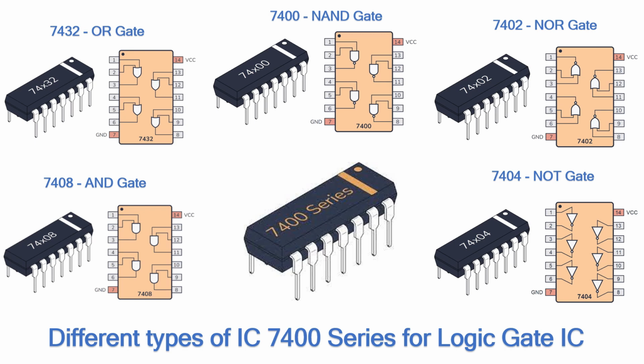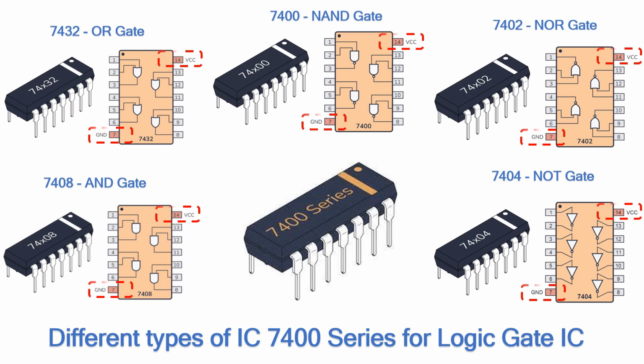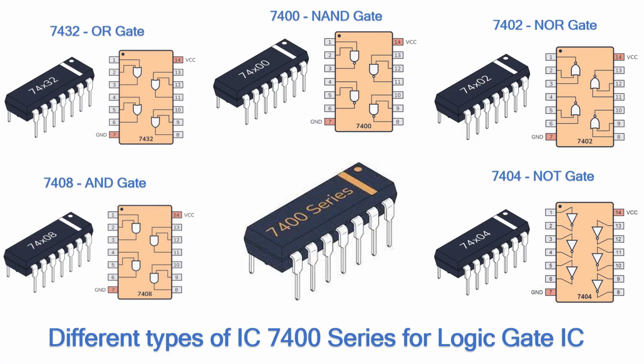All ICs have power pins, VCC and ground, where pin 7 is for ground and pin 14 is for VCC. To make sure all types of integrated circuits operate well, these 2 pins are required. We need to supply the VCC pin with 5 volts to fulfill this IC requirement to start operating.